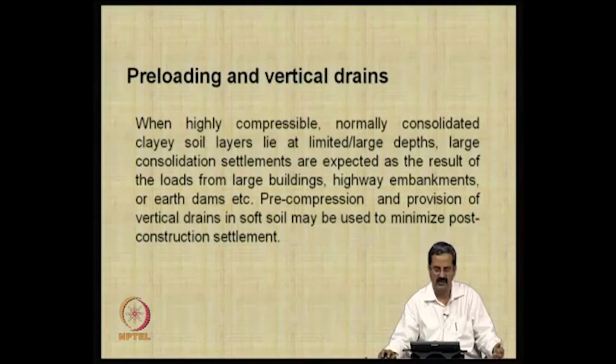In fact, all the east coast and west coast of India have soft soils. Right from Calcutta to Visakhapatnam to the tip of Tamil Nadu, east coast and west coast, and also Kandla, many places have soft soils and a lot of settlements. Many of them have port structures, and they have been using some of these techniques. Some of them are not new. They have been using pre-compression and vertical drains for more than 20 years, and we will see how they are useful in this lecture.